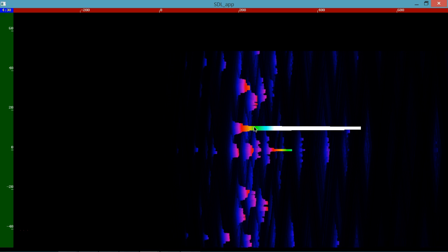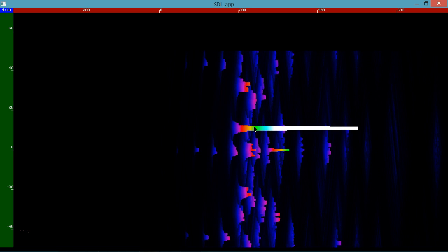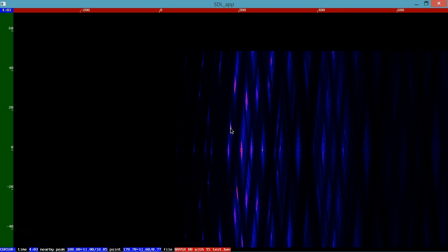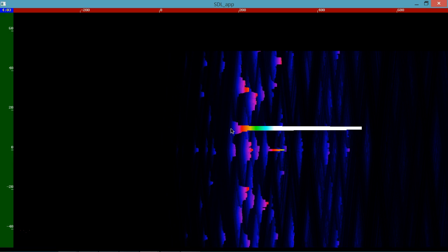All right, so let's continue on. We're going to go up, up, up, up, up, and it's at 4 minutes that we see our change. So I'm going to go down a little bit. All right, so if we were measuring that at 10 hertz right there, and then we continue to go forward, we could see the shift right there. See, it shifts positions. So that tells us that it's 11 hertz. Now again, look where I'm measuring, at the point of the very base. All right. So if I hit J, I'm measuring there. And then L will bring it back out. So that shows our point going throughout.